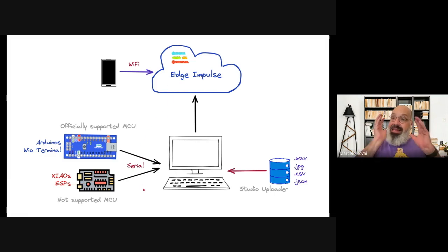But the most important way to capture data and send it to Edge Impulse in the real world is doing this offline. Because when you are doing a project, suppose that you are collecting temperature, wind velocity, wind direction from your city, for example. You collect data from maybe 1 year, 2 years, several days, because this variation is very low. It makes no sense to have your devices or sensors connected online through the serial port to Edge Impulse.